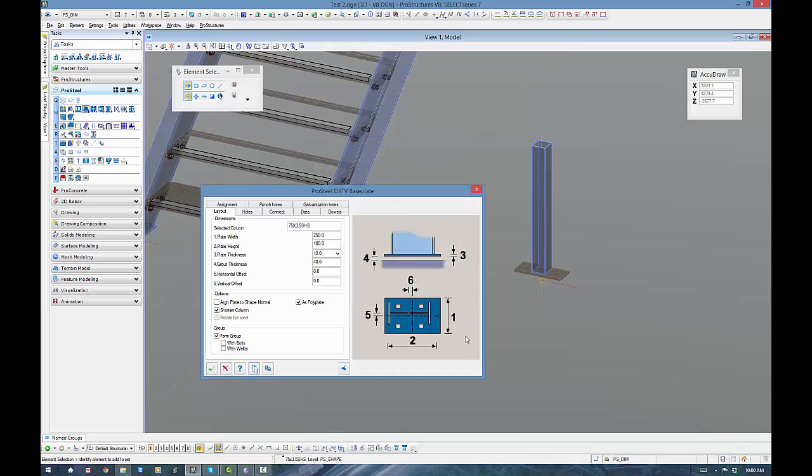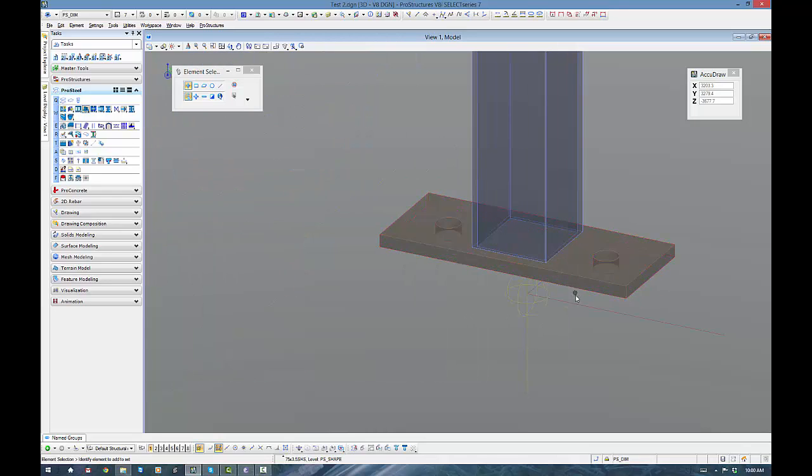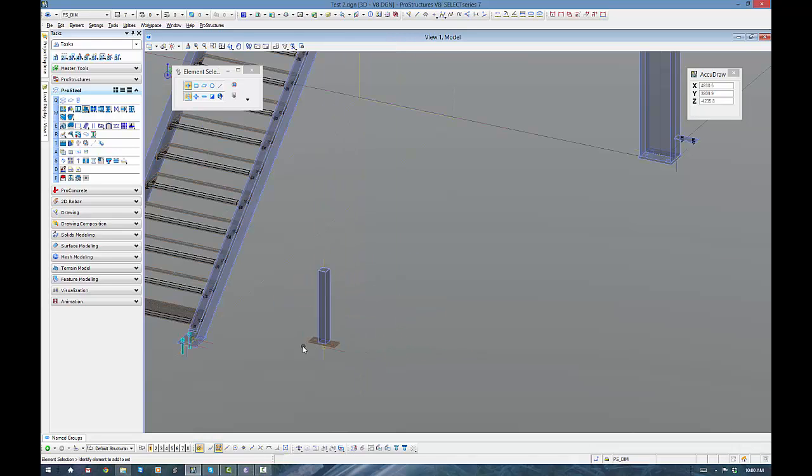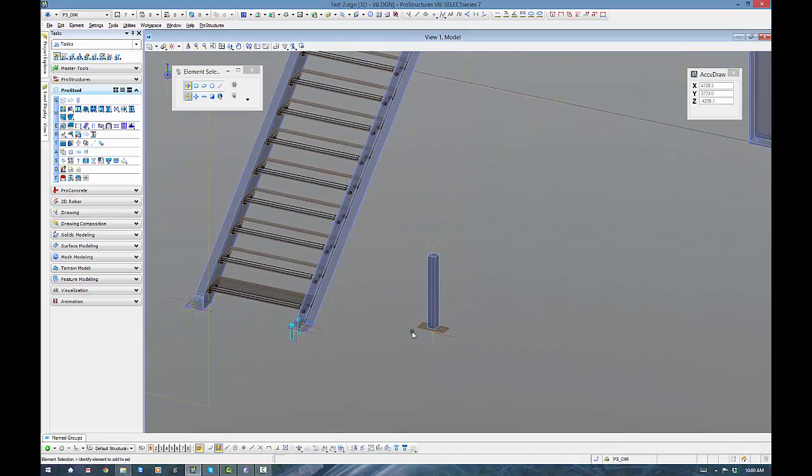So if I wanted an L-shaped base plate, I put in an automatic connection like what I've done there, and I'm going to chop this cleat in half and then copy this side over. I'm going to swing that other side around, or copy rotate. And that's how we'll get our L-shaped cleat there because we've used a logical link. So try that on and see how you go with that.